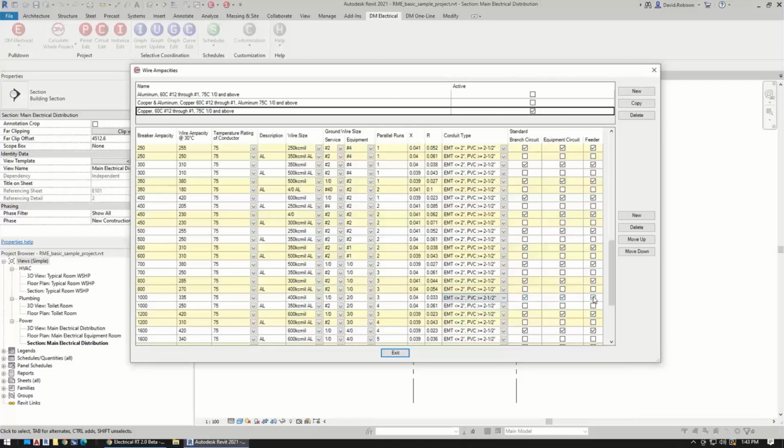The last 3 columns are whether this is a standard ampacity to size to or not, and for each configuration, for each ampacity, which configuration is the default. So this is all controlled by these sizing options up here. So we're in the copper option. That's a default with Design Master. So it's chosen all of the copper sizes to size to automatically, and you still can size to the aluminum, but by default, it's going to go to the copper.